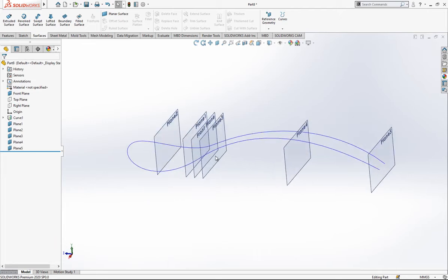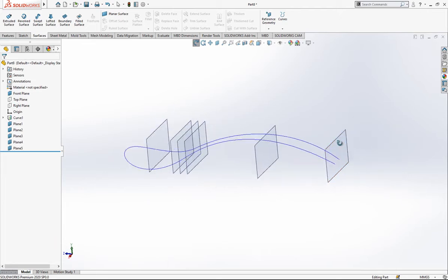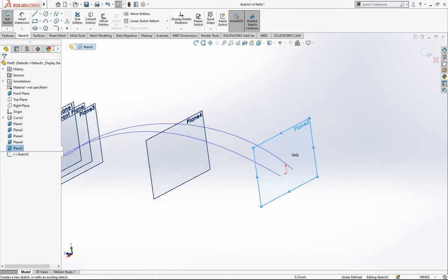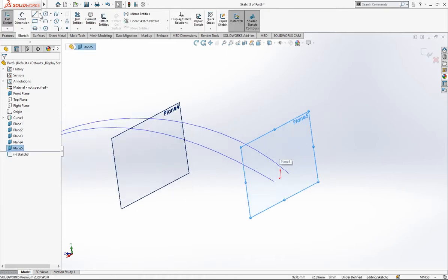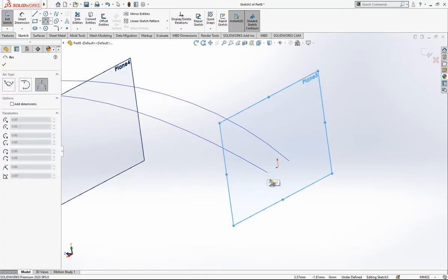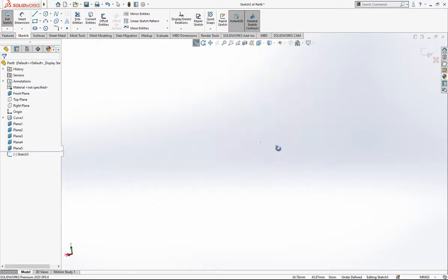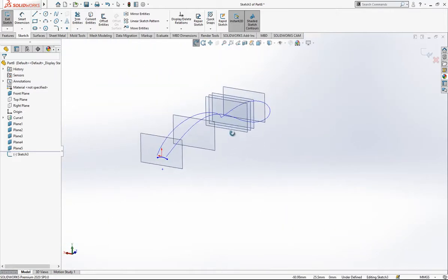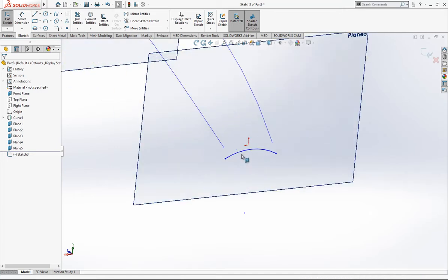sections, and let's start from behind. We click here, and then we create a sketch there, and I'm just placing here one arc on my screen. As you see, in this plane I will not look normal to, because behind is very crowded.